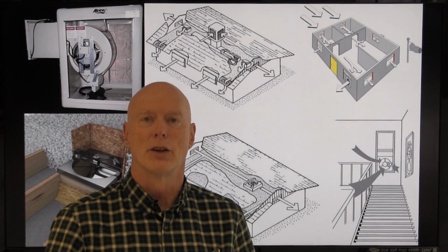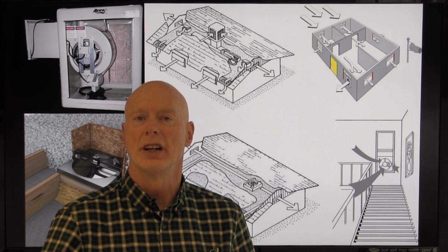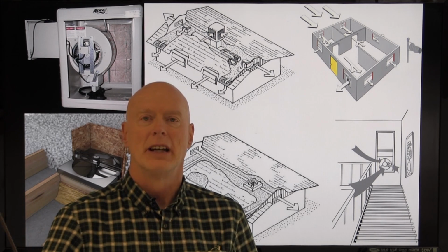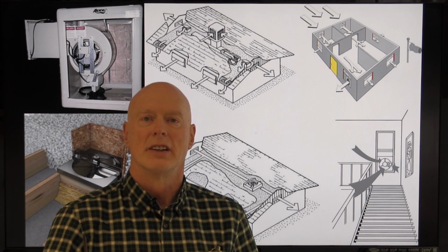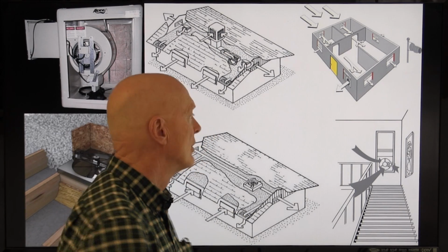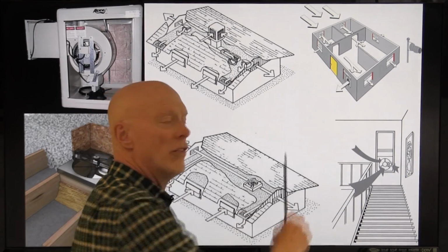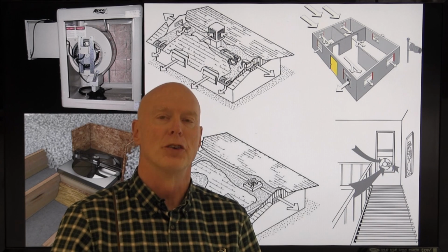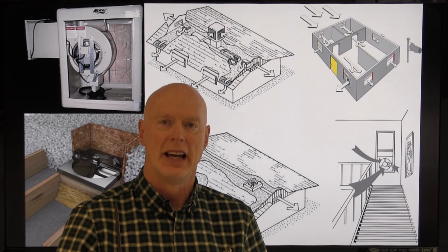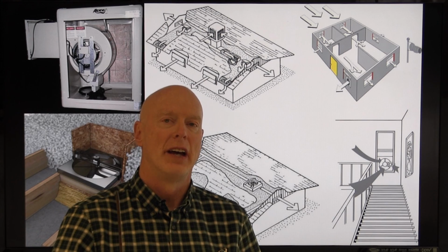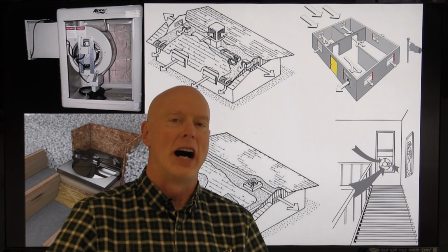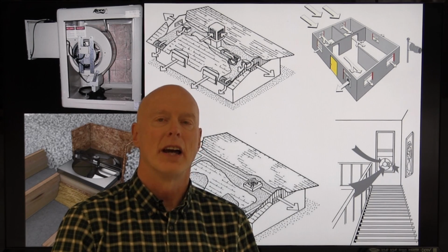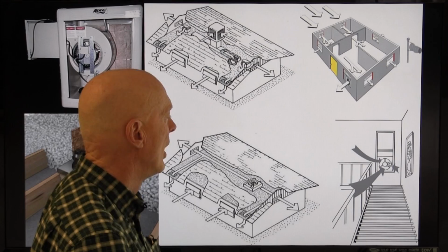So even if you live in Sacramento and it was 115 degrees today, well, it just so happens that in Sacramento's climate, it may get all the way down to the high 60s. And so you can move a lot of air through your home and remove a lot of heat from the walls and the floors and the furniture and the ceiling, and cool that house down and possibly get 5, 6, 7 hours of free air conditioning in the morning, and it isn't until later that you have to turn your air conditioning system on.